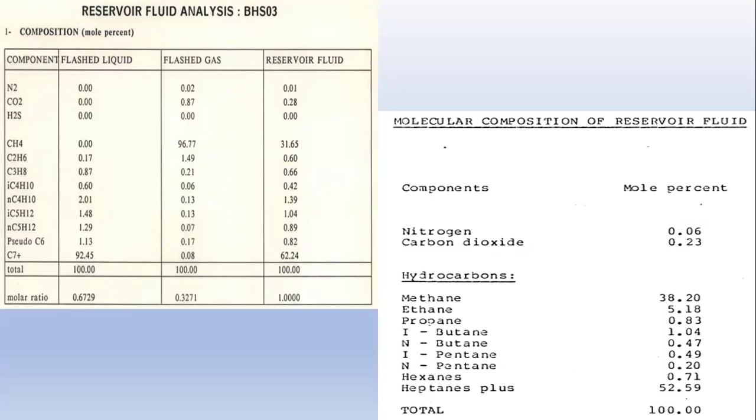but for a bottom hole sample. As you can see, you just get the reservoir fluid percentage mole directly, because in this scenario, you don't have to collect the gas sample and oil sample and recombine them to get a reservoir representative sample. This is why you collect the reservoir representative at the face of perforation. That's why you will have only one column for the reservoir fluid in mole percentage. And also, it must equal 100.